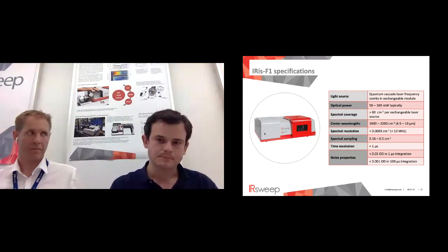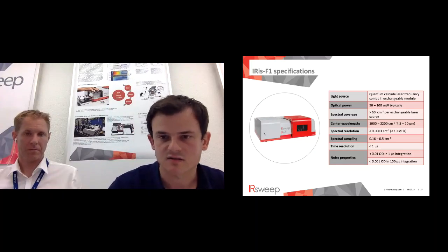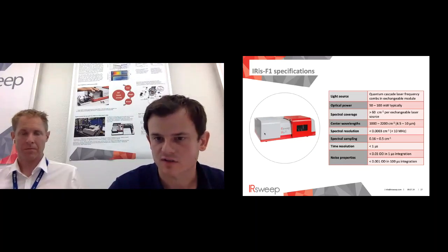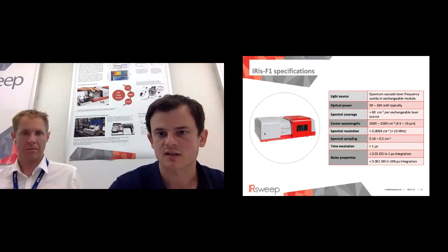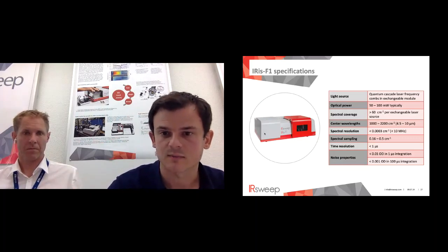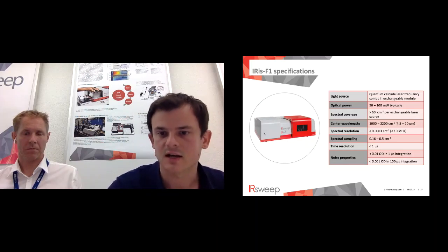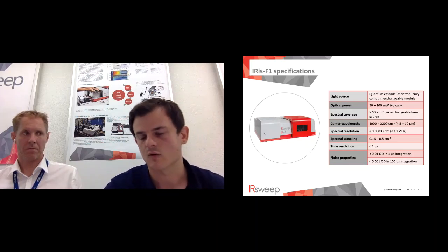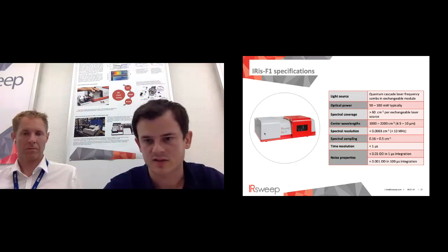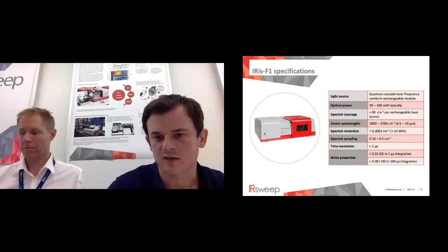The spectral resolution is, I think, up to par or even outperforms the highest resolution meter long FTIR. So it's also a feature that might be interesting for different applications than combustion, when you really want to look at only line width limited spectroscopy. Time resolution, we covered that, can be below a microsecond, up to seconds or even minutes when more acquisitions are taken. That can be done by different setups in the data acquisition systems.